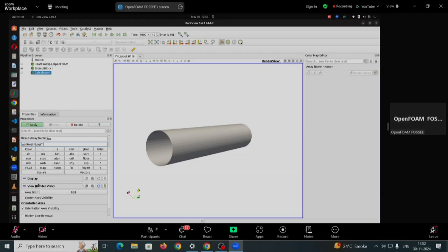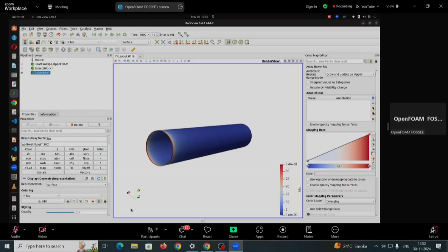So because my bulk temperature is changing, I am now saying okay, leave it. I'm just giving the inlet temperature. That means I'm calculating it based on the inlet temperature. Okay. So remember, this is not the correct approach. For this particular problem, that is flow through pipe, your bulk temperature is not constant along the length of the pipe. Generally, it varies linearly from the inlet to the outlet.